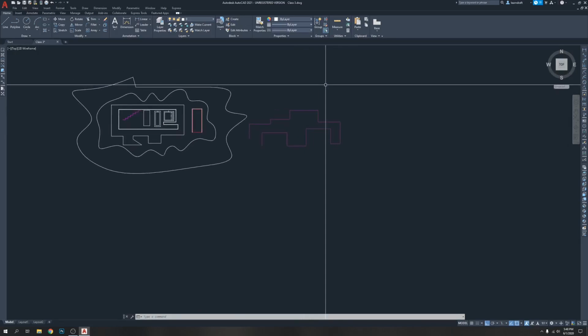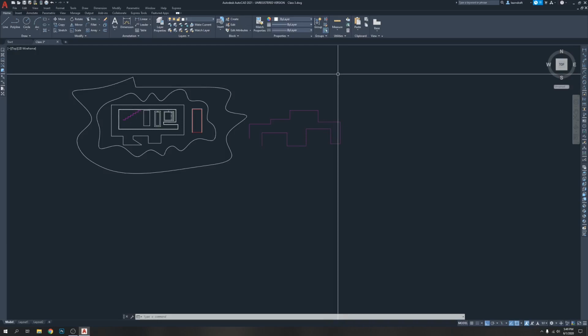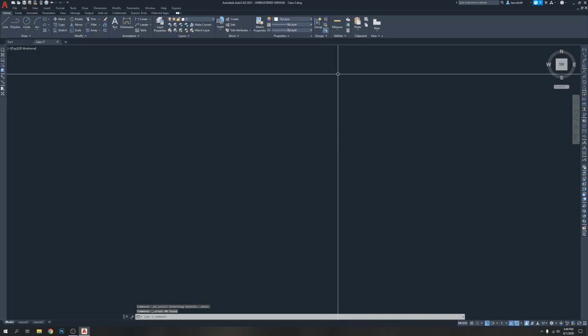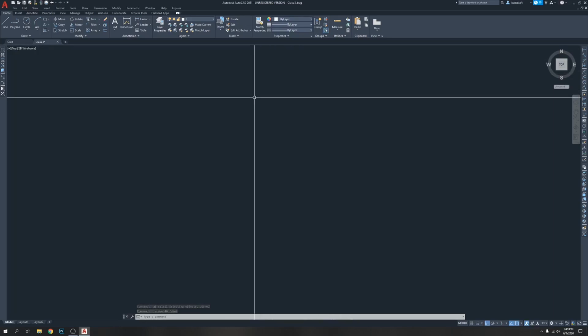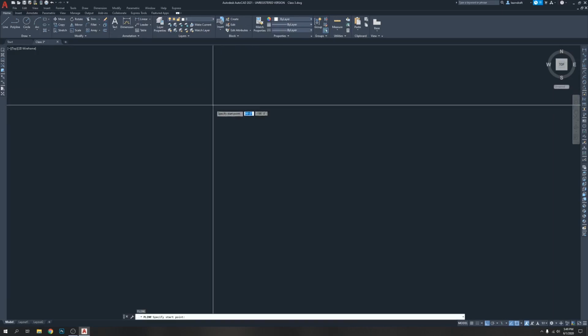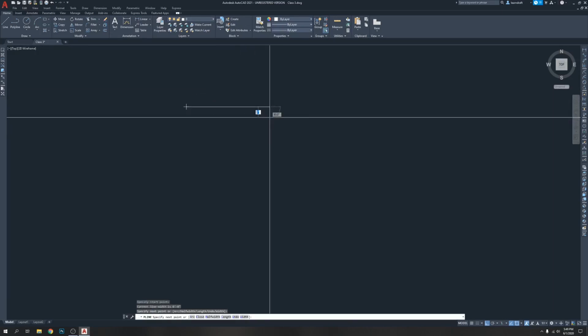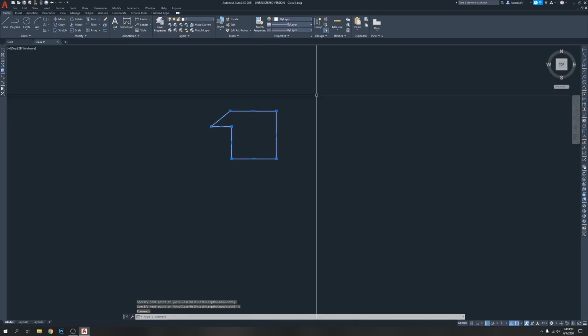Today we learned about polyline, multiline, XLine, spline, PolyEdit, and match properties. Now today's video is not too long, so let me delete everything. Ctrl A, delete. We will do it as fast as we can. Polyline, so PL, enter, click, and press C, enter. This one is together.